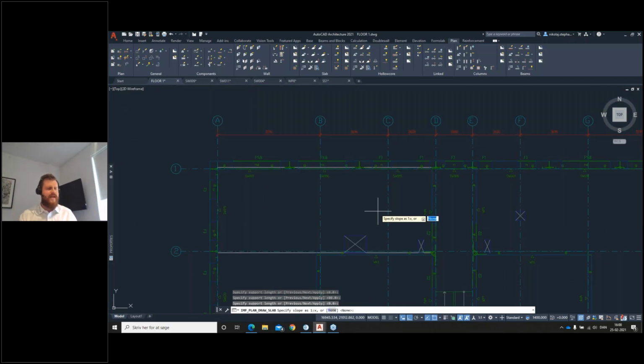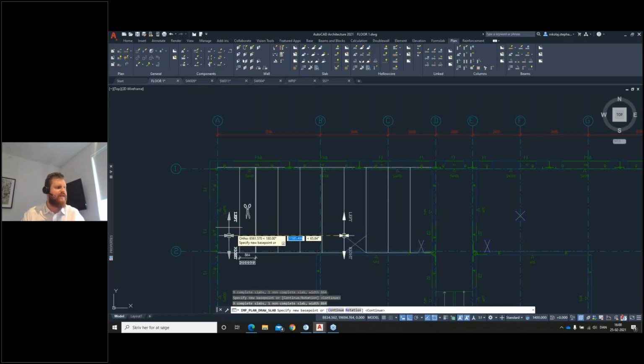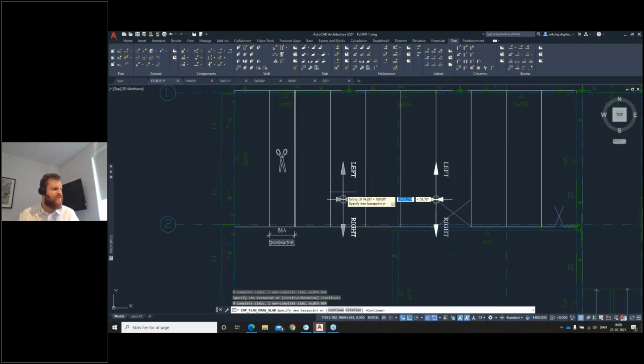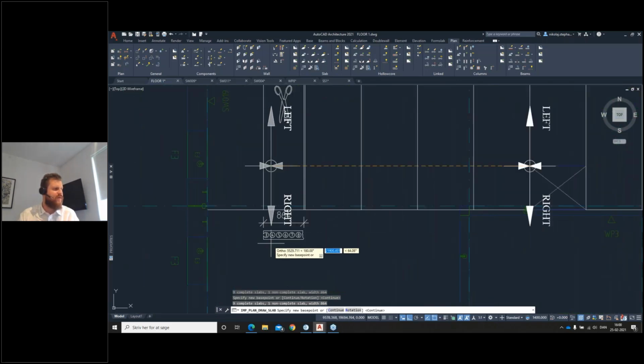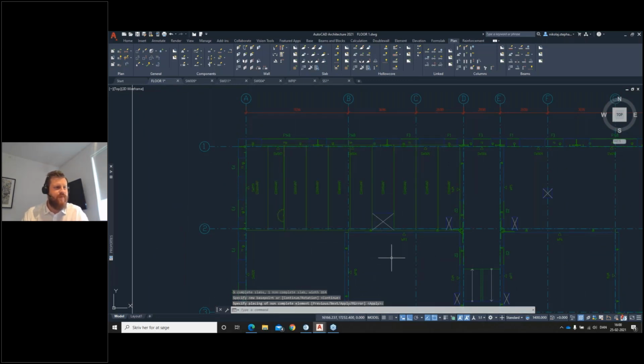I say okay to the 80 millimeters, as that is standard in here. And then I can select where I want the hollow core to start. The software will show me how it will cut and which element it will cut, which for me in this case is completely fine. Now if you notice here, I have a couple of recesses and I haven't added those. And this one is actually not a recess, but I need to shorten this hollow core down.